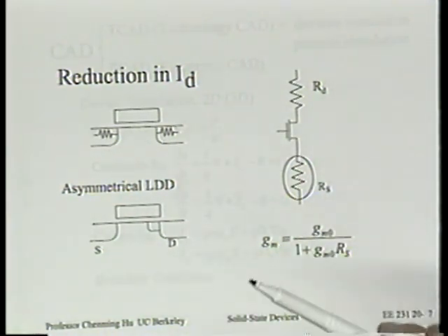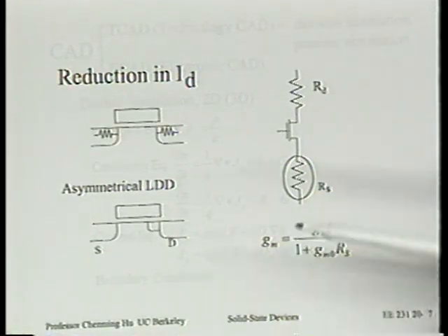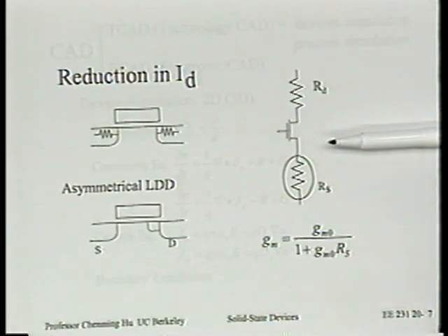We have seen a few lectures before that anytime we have series resistance in the source and drain, we're going to lose ID set. I'm focusing on ID set as a representative parameter to represent performance. We know that the entire IV curve is going to be hurt, but let's just say ID set is what we focus on.